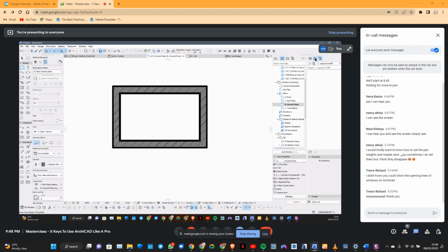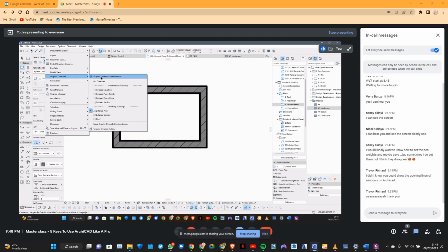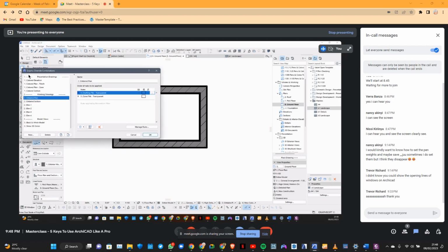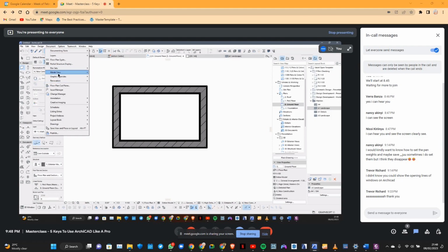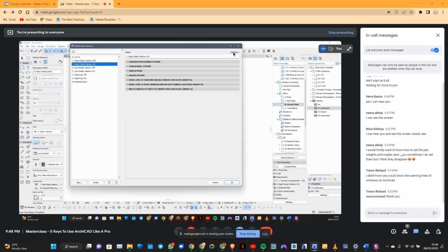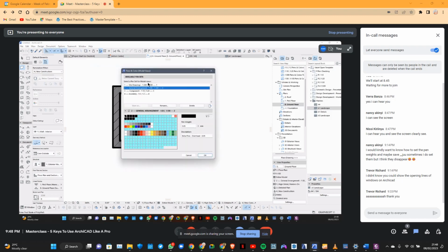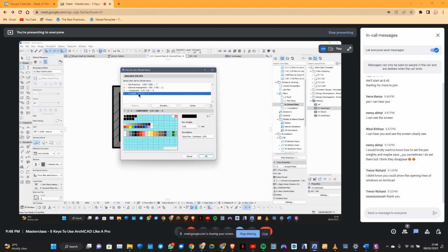With a template you get an existing file structure, you get comprehensive graphic overrides custom made for presentation drawings, you have those for working drawings, you have those for model views, you have ready-made model view options that are now relevant to how you work. We have pen sets that are now linked to scale, such that as you change the scale of your drawings, the pen set changes.